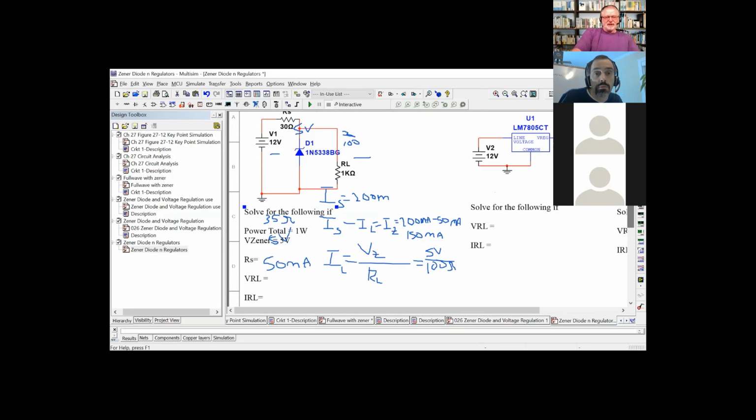Okay, so the Zener diode here is acting, you said, like a battery. Yes. And it's because it's rated at 5 volts and it's getting more than 5 volts, it's limiting 5 volts to the load. That's correct. So the rest of the voltage has to be consumed in the resistor, which is why you need the resistor. Yes, it's a small resistor right there, but the rest of it should be dumped into there. We can actually solve for that one too if we wanted to. This is a combination circuit, so it's just a matter of looking at it and seeing what we have. So if you have 5 volts to it, the rest should be about 7 volts across that, approximately.